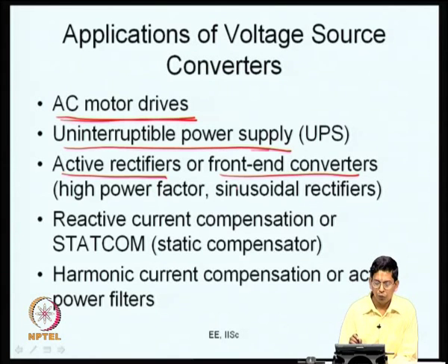If you quickly look at what we are able to do, a PWM converter with a fixed DC bus voltage is able to produce an output voltage of desired amplitude and desired phase. So the amplitude and phase are such that there is a line inductor, and it is able to control the power that flows through the line inductor.